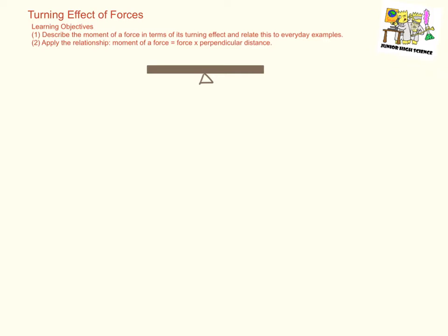You should have seen a seesaw before. Say you sit at this corner of a seesaw, you are going to exert a force, which is your weight, roughly say 700 newtons, and this force will create a turning effect in the sense that the seesaw will now rotate in an anti-clockwise direction. This is what I meant by forces creating a turning effect.